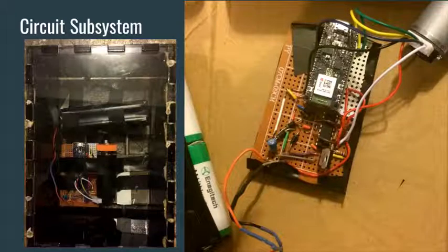And so we also have our Arduino Nano BLE, which sends signals to the DC motor, telling it when to turn and when not to turn, again based on the programming subsystem. But it does this by receiving an input signal from the encoder on the DC motor, and based on that signal it sends an output signal to the H-bridge, and then the H-bridge sends an output signal to the DC motor, telling it to turn or to stop turning.